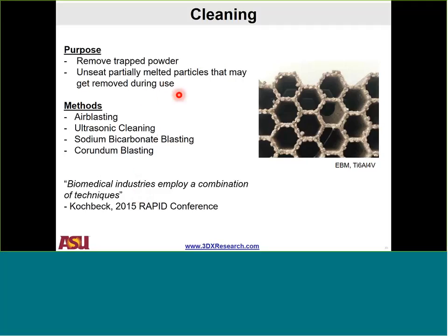And the main purpose of cleaning is to remove trapped powder, but also unseat partially melted particles that may get removed during use. You don't want a lot of loose powder falling off your implant. So the four common methods that people have studied are air blasting, ultrasonic cleaning, sodium bicarbonate blasting and corundum blasting. And from that conference that I attended, the biomedical industries employ a combination of these techniques.